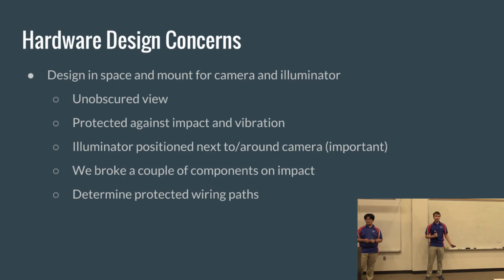And then another important thing with LEDs: make sure the LEDs are right next to the camera. With retroreflective tape, the way it works is you shine a light at it, the light hits the retroreflective tape and comes right back at it. So it's not like a normal mirror, where if you're looking at another angle, you can see it. If your LED isn't right next to the camera, it won't even see the light. We would move ours a foot or two to the side, away from the camera, when doing tests, and it would completely lose it around a foot away. So you want to have your LEDs right on top of that camera if possible, to get the best result for lighting up targets.